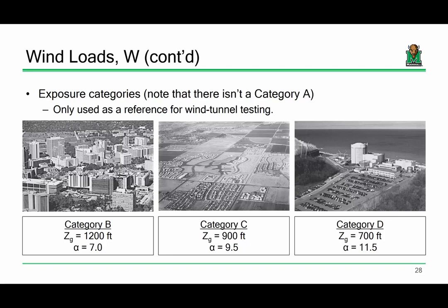That's a good question, and I'd say what's going to happen in those scenarios are really one of two things. One, you might have to encounter wind speed-up effects depending upon the topography, like if you have a building on top of a hill and you have wind speed-up effects. And there's rules in the spec for when you need to account for that or not. And two, whenever you have a special wind region.